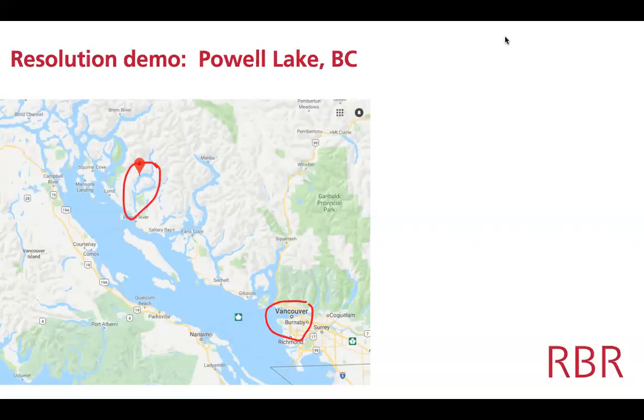Question about the time response. Conductivity has a very, very fast time response as an electrically based measurement. It's faster than typical thermistors, tens to 100 milliseconds or so, probably. Usually we're more concerned with the time response of the thermistor. Does that answer your question, Felipe?